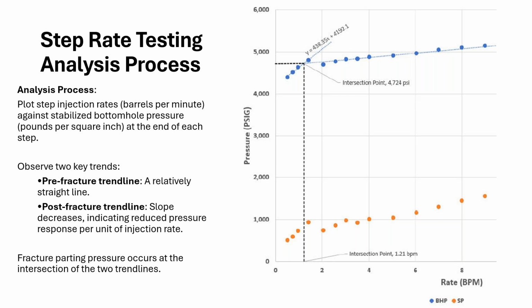Okay, I got one more question here that I have time for. With the use of downhole gauges, is there concern about adding friction reducers at higher rates during the test to prevent limitations from friction pressures? That's not a concern I've ever encountered, no. That effect wouldn't be recorded on bottom hole pressure. Regardless, it would be seen on your surface pressure. So if you're recording bottom hole pressure, then that would not be a concern.